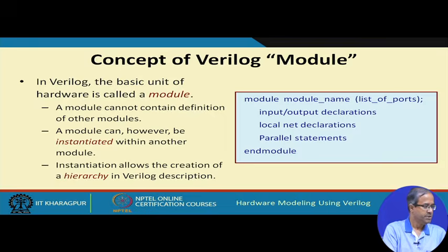Okay. So, a Verilog module in terms of its syntax contains the keyword module to start with, and it ends with endmodule. After module will come the module name, just like in C you have a function name, and within parenthesis a list of parameters. These are technically called ports, and at the end there is a semicolon, this has to be given.